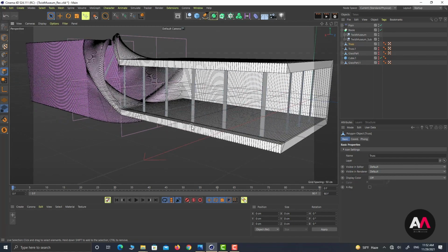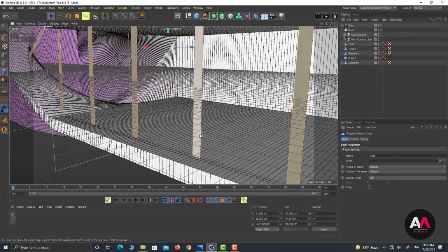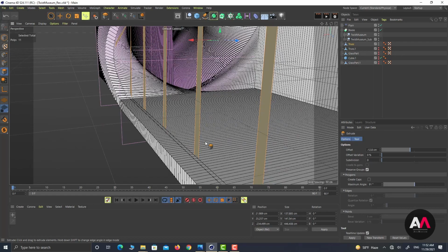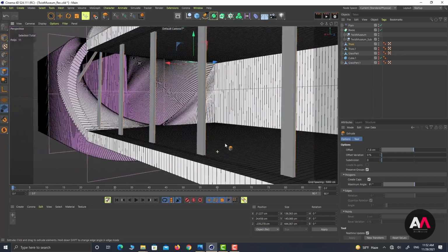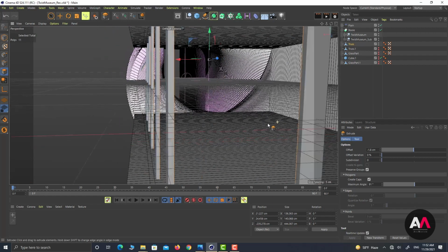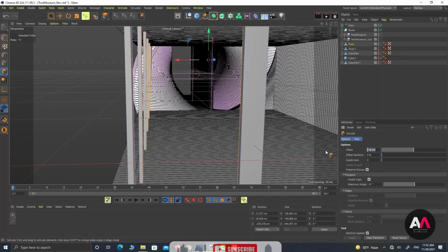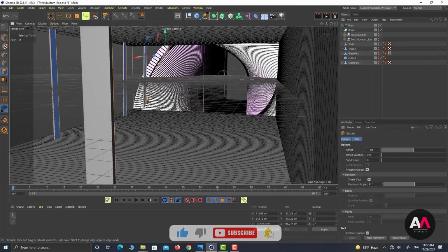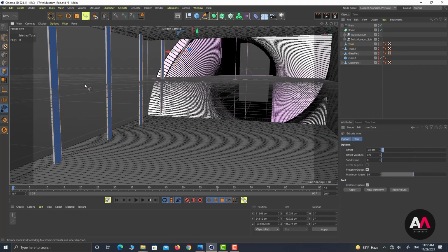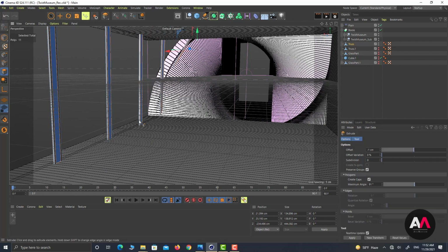So now I can come simply select all of them and use this extrude tool, extrude it inward, but the cap should be selected, and I make it -1. I'm going to inner extrude 0.9 is a good value, and extrude again, but this time the cap's off.